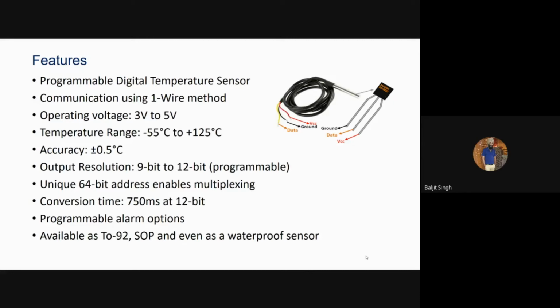Conversion time is 750 millisecond at 12-bit. But the time response of the sensor is a bit on the lower side due to this metal housing and all.